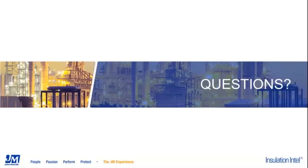Thank you, Scott. And can you clarify the Manville 1200 pipe MANDREL wound versus V-grooved in regard to ISO 15665? Both will give you the equivalent performance as long as you're using the 8-pound density in the V-groove product, which would match the 8-pound density of the molded material. All right, and just to clarify, the V-grooved has not actually been tested to ISO 15665. Only the MANDREL wound has. So while both will offer acoustical performance, strictly speaking, the Manville 1200 pipe only has the MANDREL or the ISO 15665 testing. So that's correct.